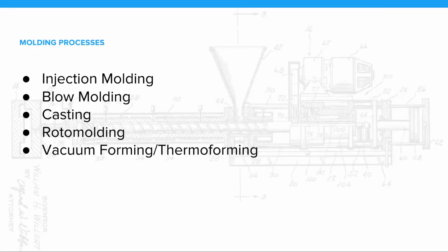These are all the mold making processes that 3D printing can be applied to. Molds are typically used to cut down production time for multiple copies of a part. They're used for materials that are not easily shaped. In the past, molds have been used to produce prototypes, but lately 3D printing has obviously supplanted that. That being said, not all materials can be used by a 3D printer, so there's something to be said for making molds for prototypes and short production runs.